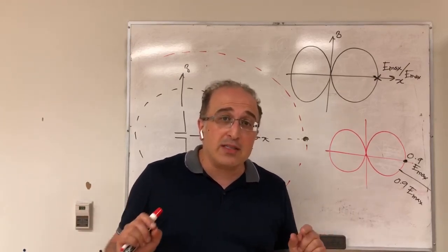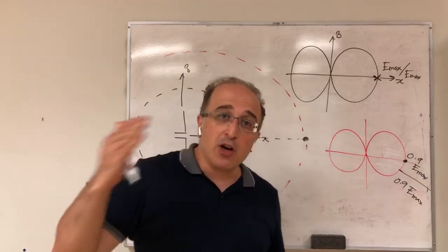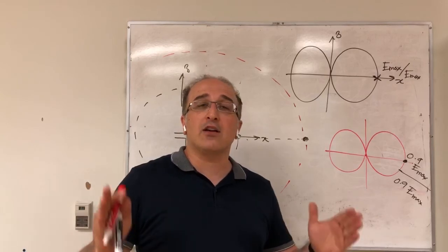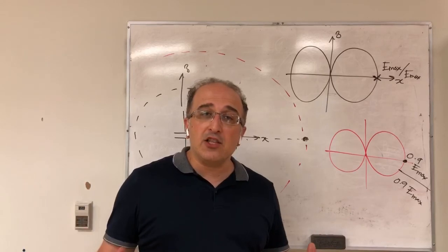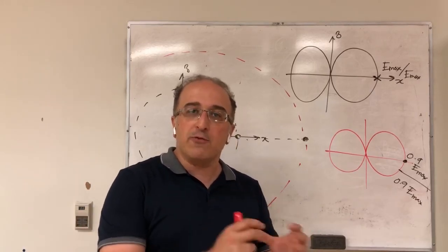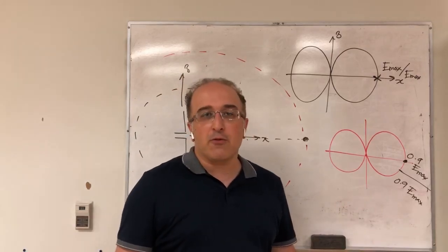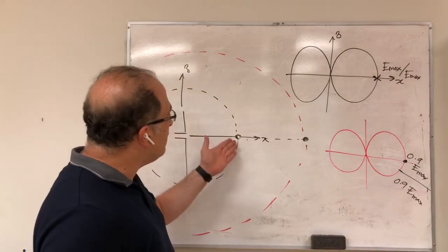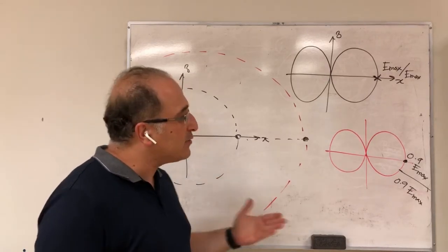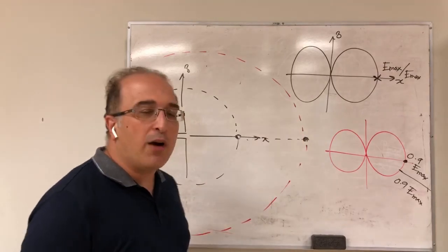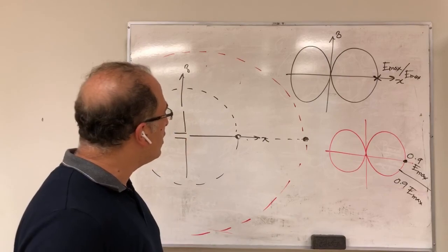If the user wants numbers, we have a different mechanism for numbers, which I'm going to teach in a different video, and that's the concept of directivity or gain of the antenna. Then we get a radiation pattern with some very useful numbers. But these numbers in the pattern are sort of useless for us, because they just tell at what distance you measured your radiation pattern. And that's why in this case, we often normalize the radiation pattern and present it as a normalized value.